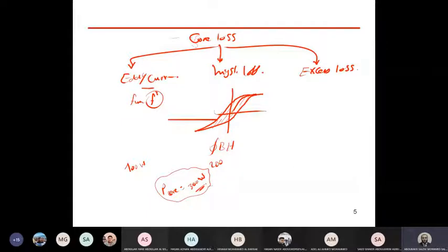The scientists did not give a certain name for this power, but they said it's excess loss, which means it's added losses to these types. They did not give any scientific name for this power, because we cannot give it a name because it's not derived, but it's just observed by experiments. So we call it now excess loss. So these excess losses are due to the harmonics, because of the harmonics coming from the power electronic converters.